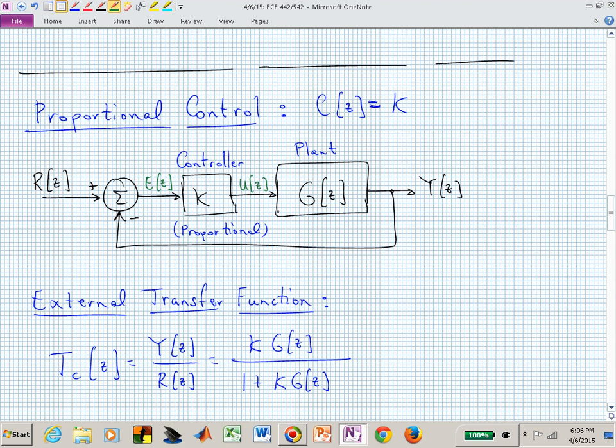So you should sit back, and in some earlier lecture I tried to talk about that, but just know that you can't do that. We learned that from the Ragazzini approach, but you can't do it any time. Okay? But you can have an unstable controller. You could plop a pole outside the unit circle, and that might benefit you. You just don't want that pole to cancel an unstable zero, or you don't want to cancel an unstable pole with an unstable zero. That's what you want to avoid.